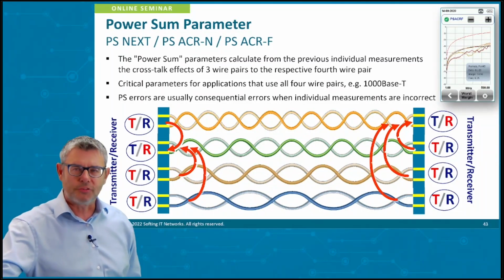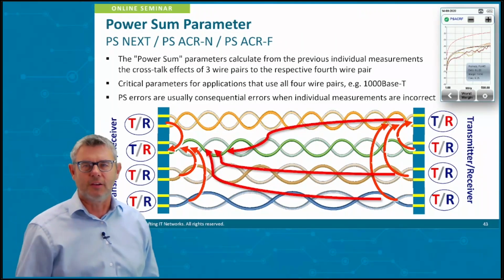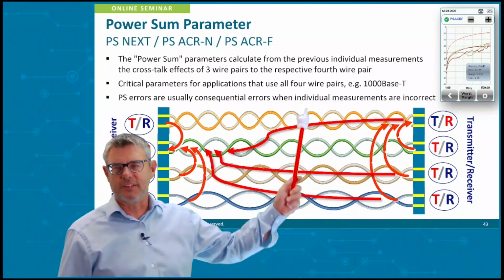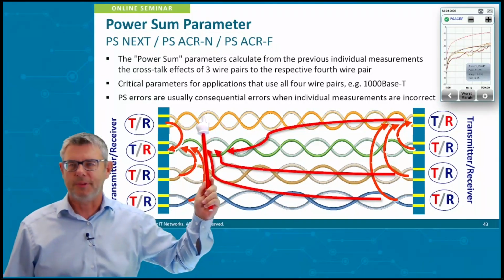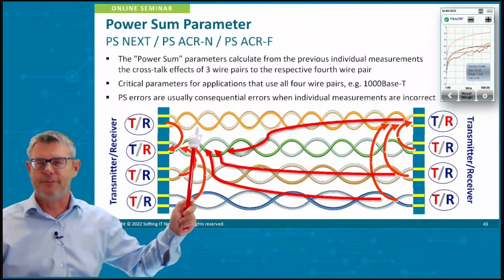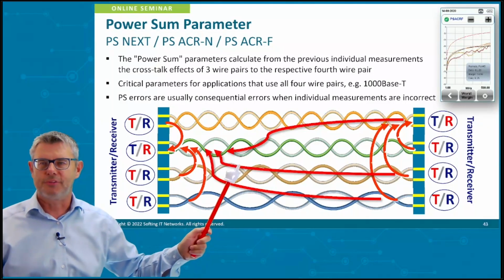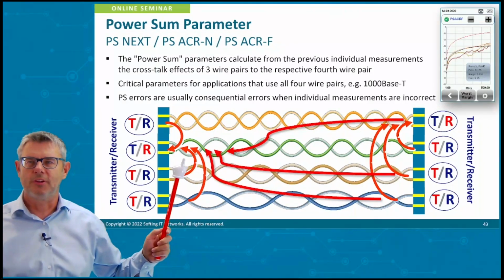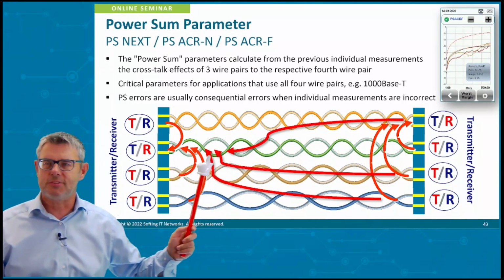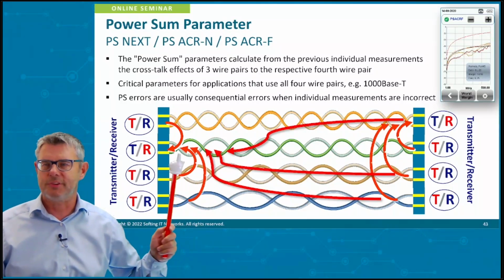No, because we have full duplex signaling. The other 3 lines here are also sending signals down the line to me here. And what's happening here is far end crosstalk. So instead of the 1 disturbance we had earlier, now we have 6 disturbers for every receiver.